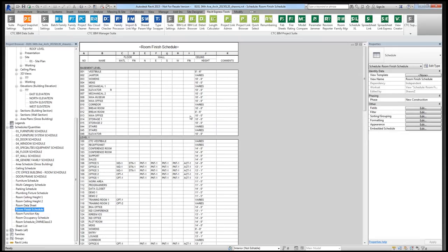From the finished schedule, if they decide they want to make a change to this, or they're working on a room directly and realize that it has a varying ceiling height, they can check that one box. I could even include it here in my ceilings or my room finish schedule temporarily, and make it a hidden field before printing. But all they have to do is run that routine twice, and then it goes through, and it's pretty quick. It goes through and updates all of my ceiling heights instead of them trying to do it all manually. Again, it grabs the upper elevation of the ceiling.